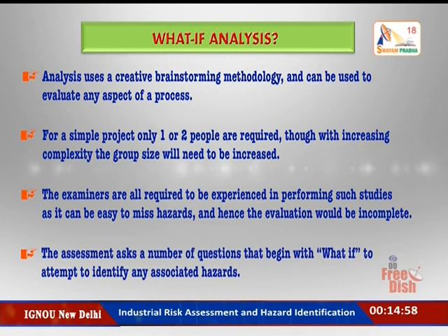So the assessment procedure is a number of questions that begin with "what if," to attempt to identify any associated hazards. So normally we will use this. Suppose this plan fails, next is "what if." These answers can then be further developed by examining specific conditions. What if the raw material is the wrong concentration? That could be further developed by evaluating, what would happen if the concentration was doubled?